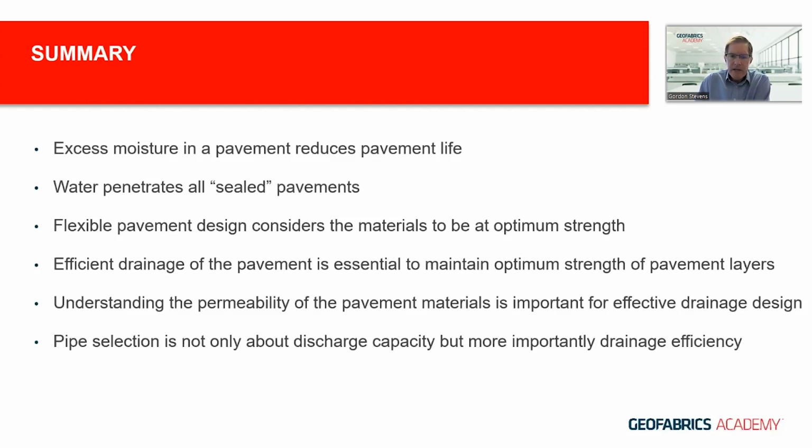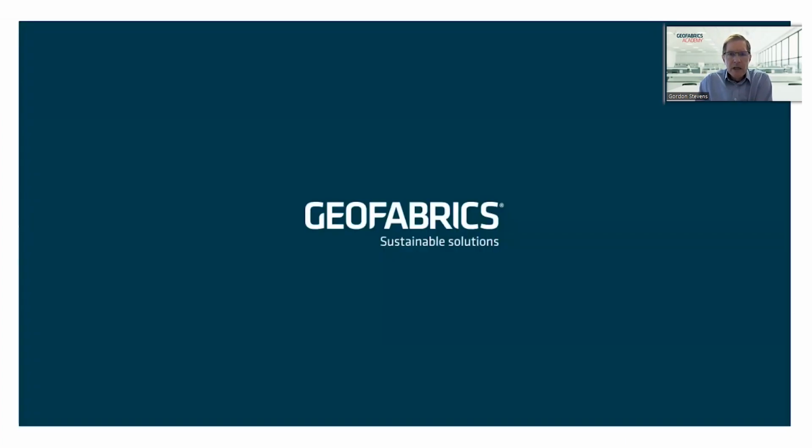And lastly, when it comes to the costs, and something that engineers will always ask, when you look at these Megaflo panel drain systems, typically because it's less excavation and less drainage fill material, the system comes in somewhere in the order of 15 to 20% cheaper than that of a round pipe system.